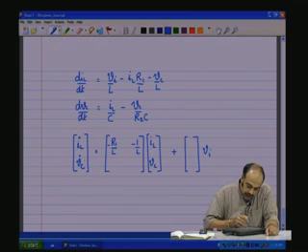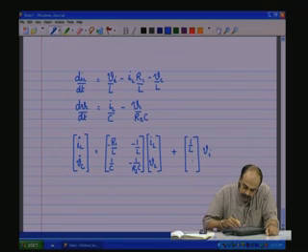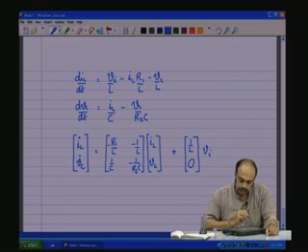Then for the second equation, dVc by dt, Vc dot equals IL into 1 by C, and Vc into minus 1 by R2 C, plus here you have 1 by L into Vi. There is no Vi term here, that is 0.